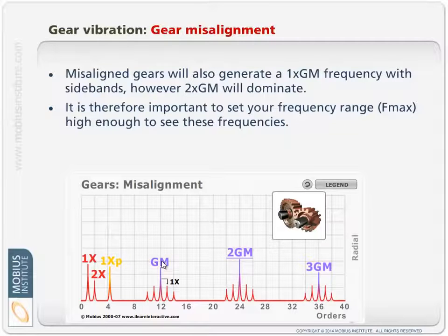Bearings, pumps, whatever the vibration is. It's really helpful to be able to relate what you're seeing in the vibration to the machine, because then you don't have to remember wall charts and so on. You don't have to just take guesses because, well, it sort of looks like that. I mean, this is a big call you're making. Do I stop this gearbox? Do I have to order parts? And they could take a long time to be delivered. It could be very expensive. It's really important that you get it right.